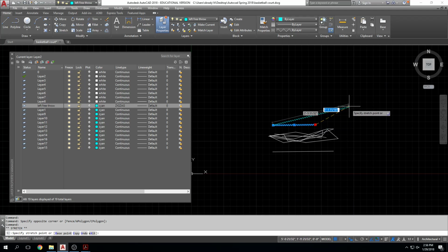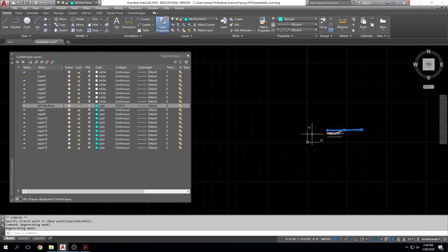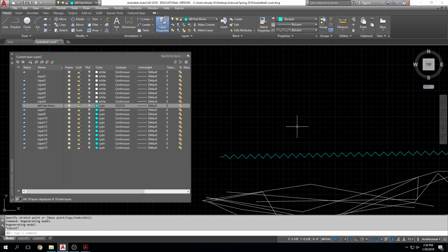That actually solves a problem I have in AutoCAD. Glad you mentioned that. I have a question. Can you draw multiple line types on one layer, or only one per layer? One per layer. So I can't assign more than one here. But I could create a new layer that's almost identical in nature and name and give it a different line type. You should probably copy a layer then. Yeah, if you create a new layer out of this one right here, I click on new, it's going to copy it. Yep.